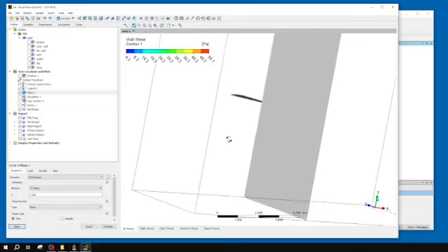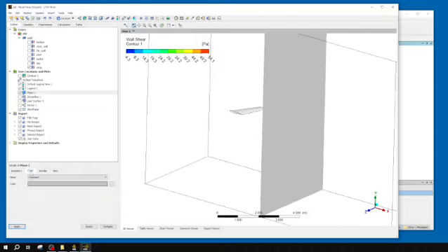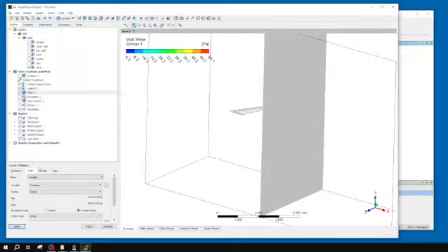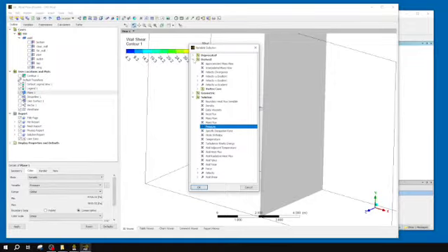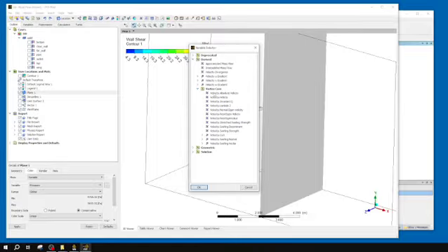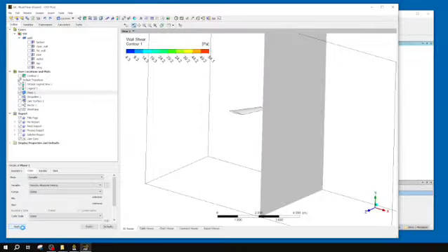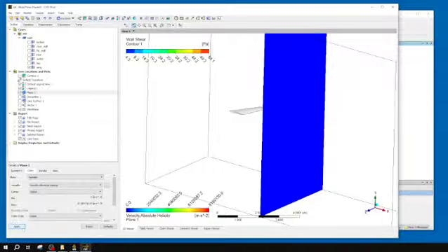Generally, I don't love seeing these planes, especially as a constant, they're rarely beneficial, but I'm going to show what they look like as a variable. My specific variable is going to be one of these derived variables, a vortex core, because I love my vortex cores. And let's go absolute helicity. I'm going to apply that. It'll take a little bit to load because some of these derived ones, it doesn't expect you to use, so it has to calculate what it is.